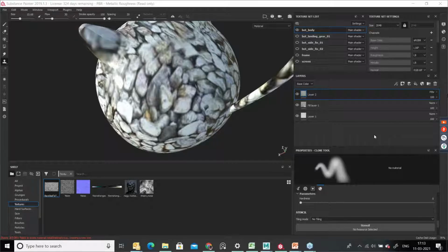Projection process I explained, and yes, does the clone tool work for smart material? Smart material, it depends. You can try, because we have to see directly. We can't do any changes in the smart material. Above the smart material, you can create one layer and make that layer a pass-through layer. Then you can pick the information and try to remove the smart material. Mostly that border won't come, because when you have a smart material, it's always smart. So it will work for you.